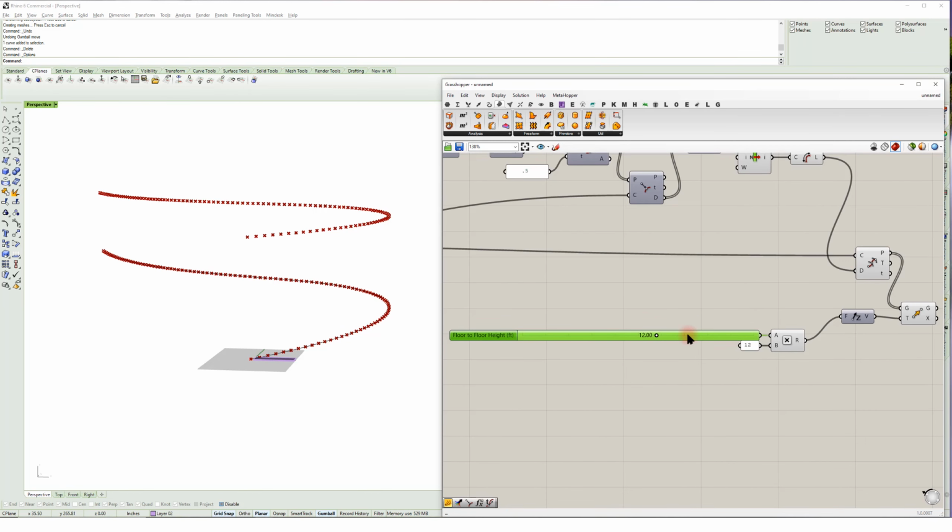Next thing I want to do is another slider. I'm going to go 1, and if you're real smart, you can look up the International Building Code by saying 4, because you can have a riser no less than 4 inches. Less than 7, actually let's do less than 6, less than 7.0. That gives me an extra decimal. And I'm going to call this riser height in inches. Those are healthy constraints because that's building code. You can't go more than 7. So don't build higher treads than you're allowed.